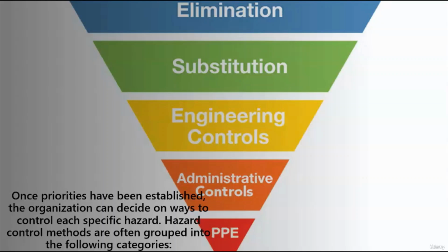Okay, so in this case, they may wear a nose mask or a goggle or a face mask or a helmet or overalls, and all of these are aimed at ensuring that the hazard that is still present does not get to the worker. But the idea is that in any situation, when there's a hazard to be dealt with, you look at elimination first and then substitution and then engineering controls. If the hazard or the risk is still considered high, then you look at further controls with administrative controls and then PPEs. At no point should you as a safety practitioner just go straight and implement PPEs.